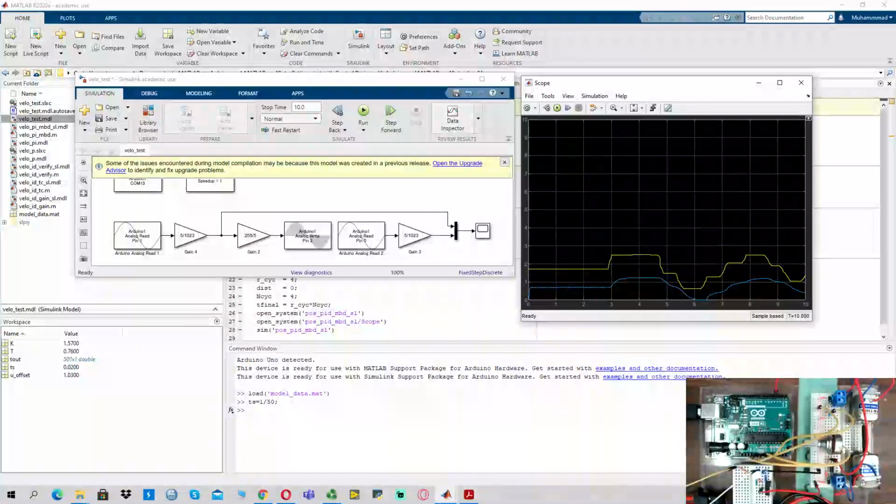The proportional controller will keep working until there is a deviation from the target value. If there is an error, the controller will keep pushing to make it 0, but the proportional control will never be able to make the steady state error 0. That's why we need integral control for eliminating the steady state errors.